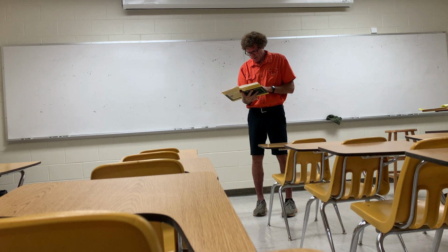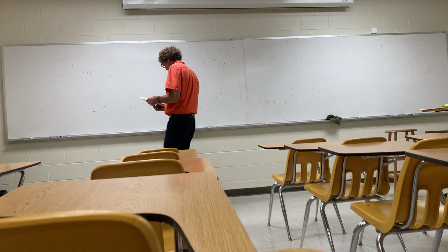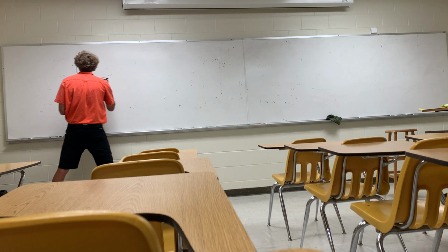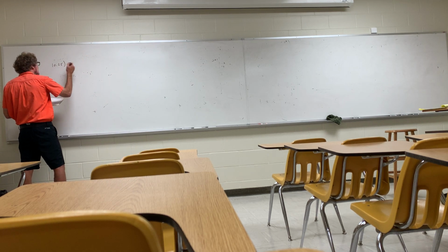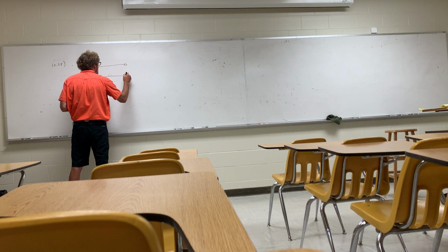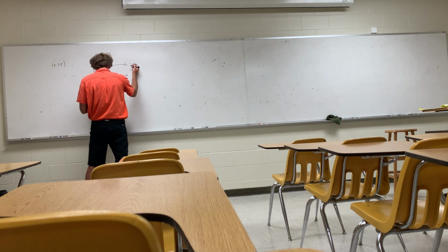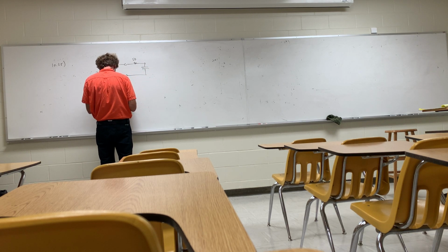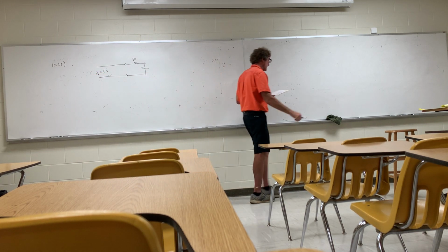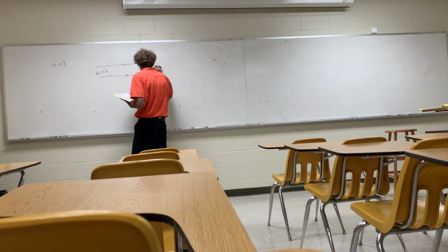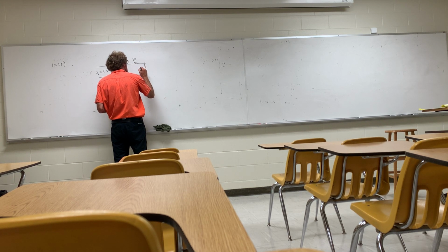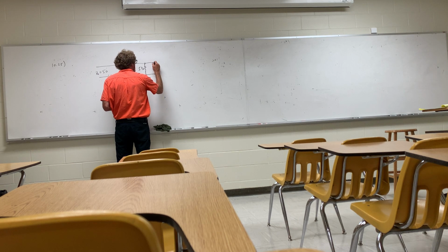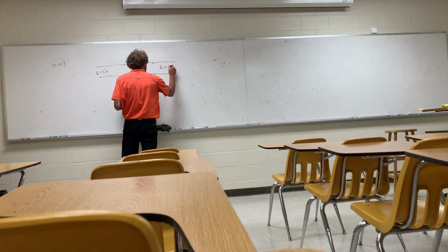So we're going to have a 50 ohm transmission line. This is problem 10.25. Got a transmission line that has 50 ohm. Cut it, and then you put a 50 ohm resistor in series, and you shunt it with a capacitor, oh, I'm sorry, shunt 50 ohm resistor, not even a capacitor. This is just going to be a 50 ohm resistor. And then it's connected back to a transmission line with a characteristic impedance of 50 ohms.